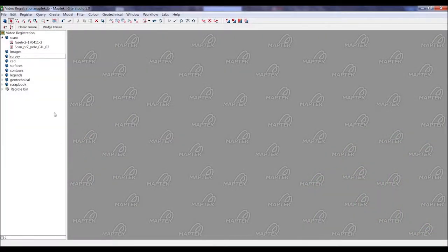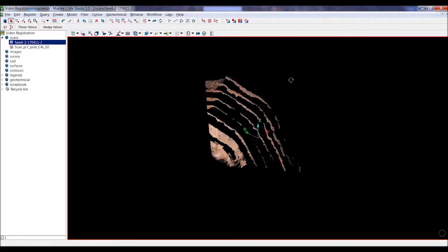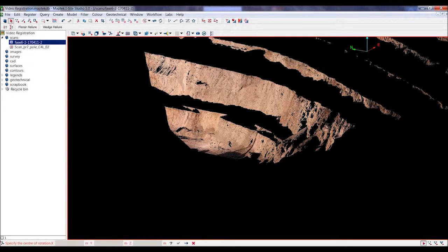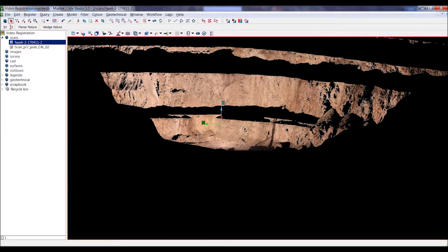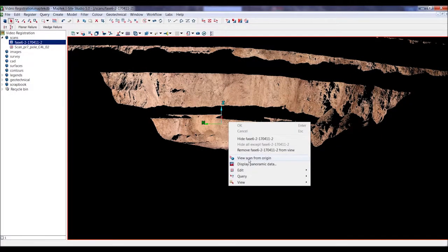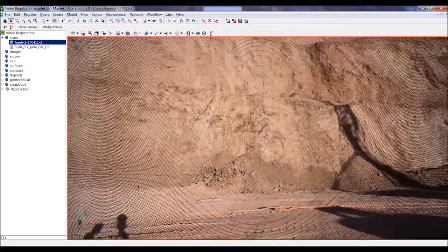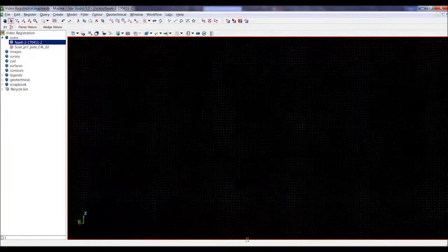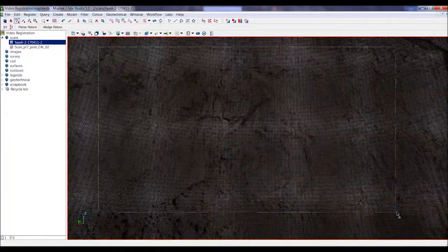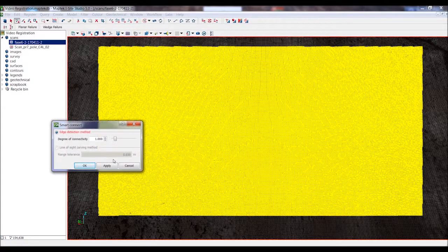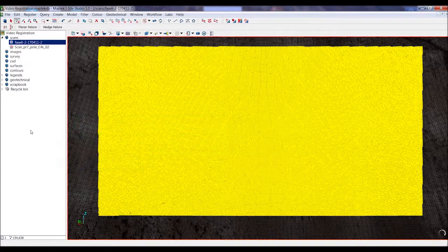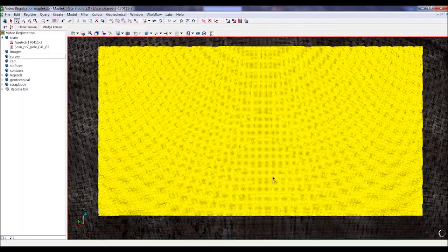Today I'm going to show you the image registration option in Eyesight Studio 5.0. The aim of this tool is to drape any image on top of any surface. But for the example today we will try to drape an image on top of an Eyesight scan triangulation. As you know, Eyesight scanners are able to capture the points and the image simultaneously. So for example we can watch the points and select some points, connect, and drape the image automatically.